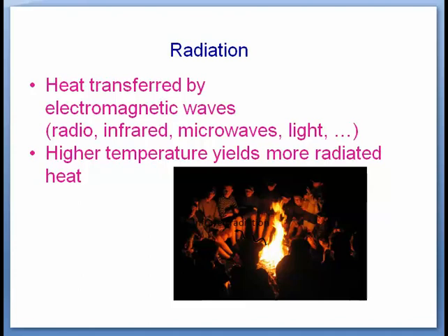Similarly, in the first pass, that is the radiant pass of the furnace, most of the heat transfer is because of radiation. Radiation does not require any media. And in the second pass, mostly where the LTSH and economizer are, the heat transfer is because of convection.